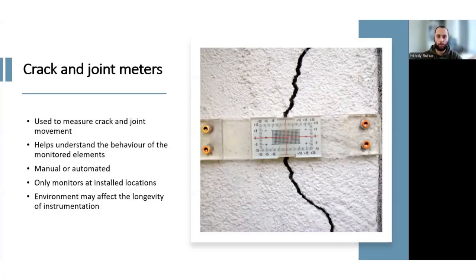Generally, when needing to monitor multiple cracks, you will install many crack meters, as they only really record data at their installation points. So depending on the placement as well, they could be in danger of being exposed to the environment or other factors, which may compromise their longevity.